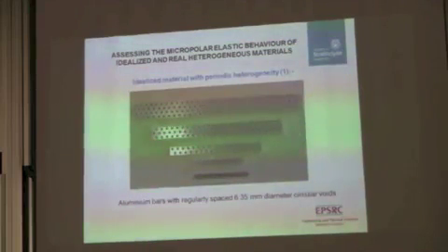These are straight beam samples, and they are just machined up out of aluminium bar stock. The largest sample here is about 0.5 metre long. And you can see that as we go down here, the samples are getting smaller, but when we load them, we keep the aspect ratio, the span to depth ratio, the same. All these aluminium bars have voids of this size, and they're also arranged so that the void centres are on this triangular array.